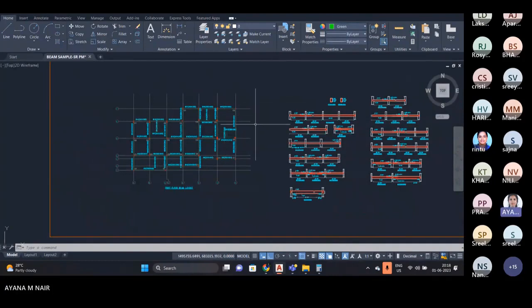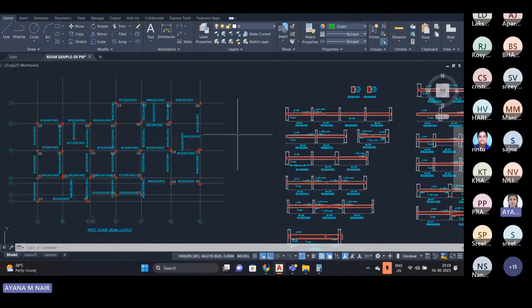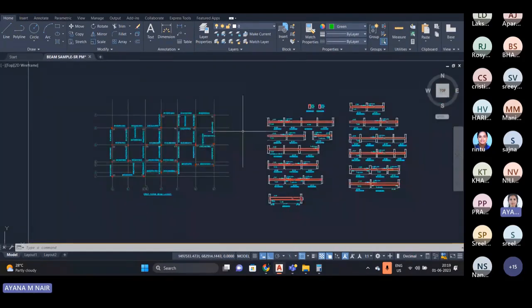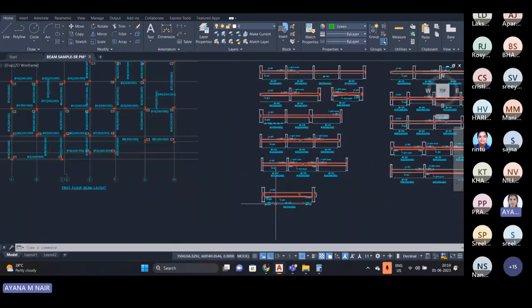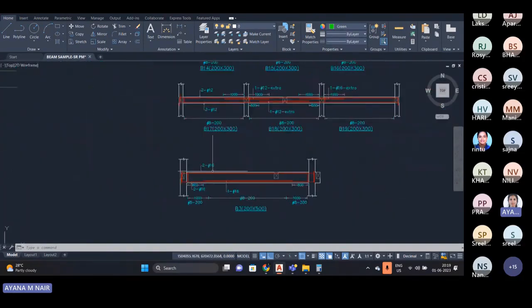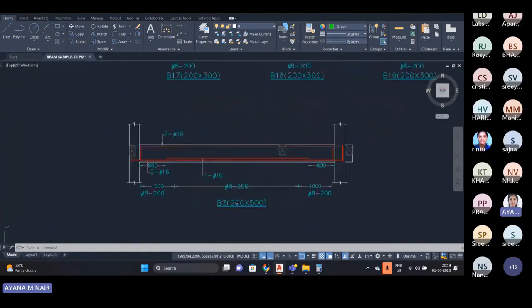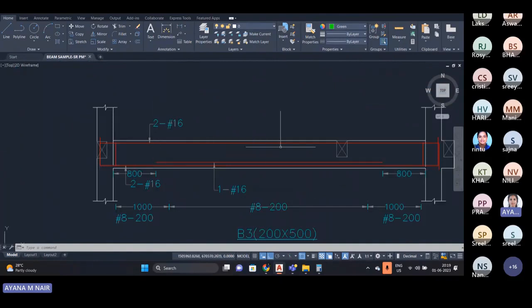Yes. Okay, let's begin the beam drafting for the BBS section. First, the structural department will provide us with the beam column layout. We have two types of beam section. First one is the detailed drawing of the beams, like this P3 beam. Here they are providing all the reinforcement, stirrups, and all detailings.